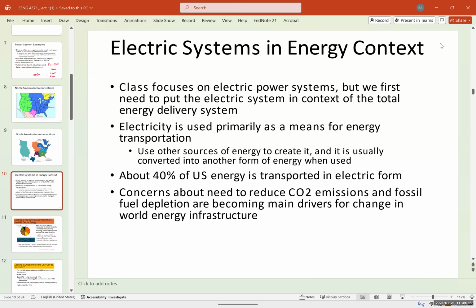Still, there are some disadvantages as well when you convert one type of energy to another, for example, gas to electricity. You have about 30% efficiency. So if you get 1 joule of heat from gas, if you convert that to electricity, you get 0.3 joules. So you lose like 60-70% of that. That's the reason for heating, if you have gas, it's going to be much cheaper and also much more efficient compared to if you want to heat your house with electricity.